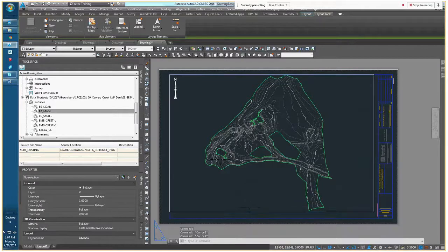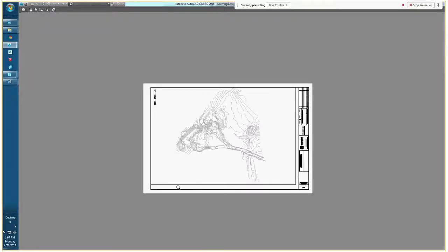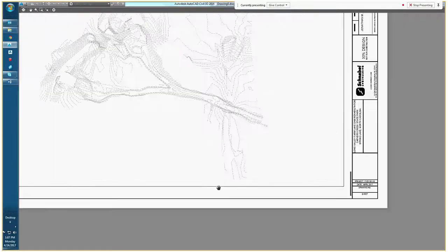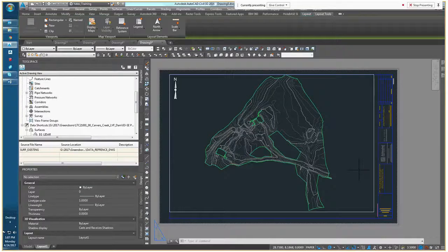When working with viewports, there's a couple things I'd like to point out. Right now, it created the viewport based on the mview command on the current layer, which was layer 0. So if I were to print this drawing, we would notice that we actually see the outline of that viewport because the layer it's on is a plottable layer. So for most cases, for most drawings, for most projects, we would want that viewport on a non-plot layer like